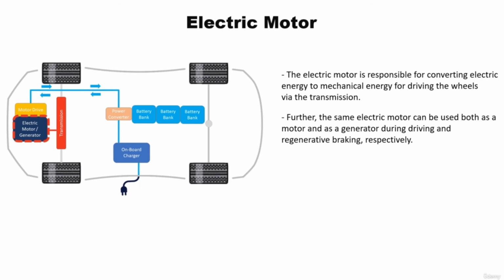On the other hand, the power electronic controller directly controls the different power converters and hence indirectly the operation of the battery, motor and the vehicle. It uses the driver's accelerator and brake pedals to control power flow and select the operating mode between driving and regenerative braking. It controls the onboard charger and the battery charging together with the battery management system.